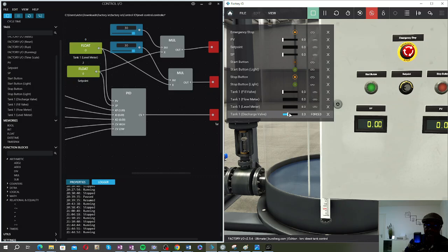The set point is what I want to achieve, and it's also from 0 to 10 volts. But in the program, as you can see, I've done some conversion to make sure that it tallies with the 0 to 300 liters that we have here, or 300 centimeters. So I'm assuming that each centimeter corresponds to a liter, so we have a 300-liter capacity tank. But what is more important is just to get the concept, not the actual value. It's just an example.